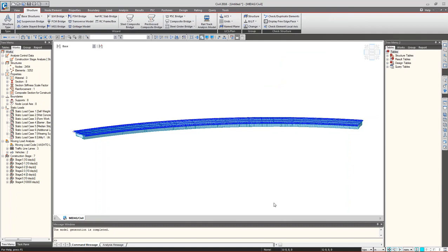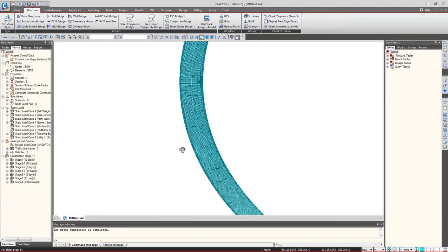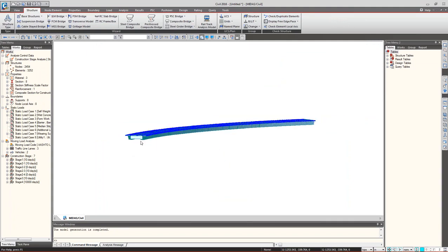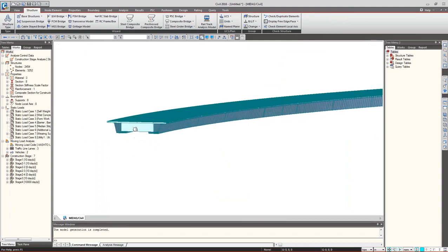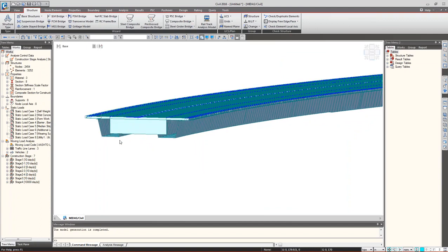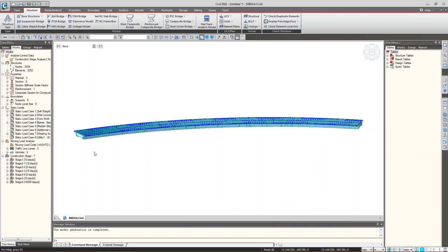And you have the full model ready in front of you. So this is for the end diaphragms. Many people tend to give a diaphragm covering the full top section. You can do that way also. It's up to you how you want to do the analysis for the bridge. Some people prefer just giving an end diaphragm like this, so you can provide an end diaphragm like this.